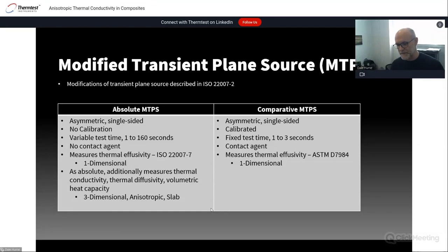When the factory or the user are able to calibrate that sensor, they need to isolate the range by having multiple calibration points so that that sensor can calculate the heat losses or calibrate the heat losses that are in the sensor. So it's not an insulation use, it's a different construction that requires you to associate multiple calibration points to populate the difference, how much heat is going through the heat sink, through the sensor itself, and how much heat is going into the sample.